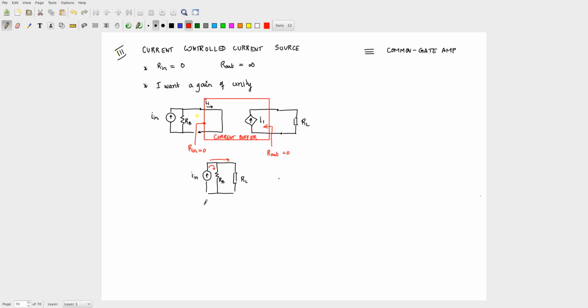Okay, this is the connection without the buffer. Did I say current through RS is 0? If I said that, it is wrong. Thank you. Current through RS will be 0 with the buffer. Over here, work out In is here. What is the current? So if I call this I alpha and this I beta, can you tell me what I beta is and what I alpha is? Okay, which one is which?